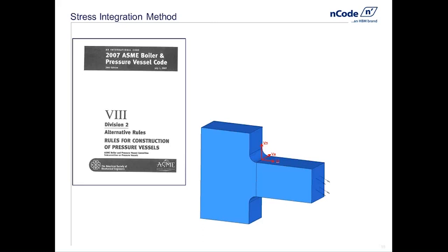The overall technique starts with a model where I have a weld I want to analyze, and all we really need to do for DesignLife is describe the location where I want to do this weld calculation. So here I have that coordinate system that you see, and the origin of that coordinate system is just a location in space where I actually want to do this analysis. Again, that location doesn't have to necessarily be a node location or on an element edge. It's just a location in space, relatively close to the surface in question. The other input for this is just a vector. Here you see VN is a normal vector that's going to describe the direction opposite where I want to drill through the solid to do the linearization.